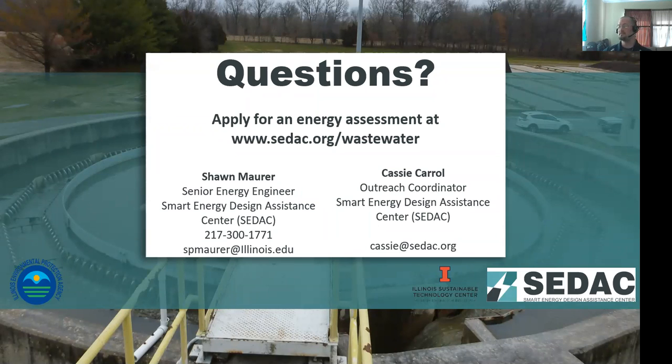But we've looked at, for smaller plants, a completely air-driven pumping system that had kind of natural flow recycle from the clarifier section, but it's for very small flows up to 300,000. But it had very low energy intensity for that system. We've also looked a lot at a system called the algae wheel, which is essentially a rotating biological contactor system.